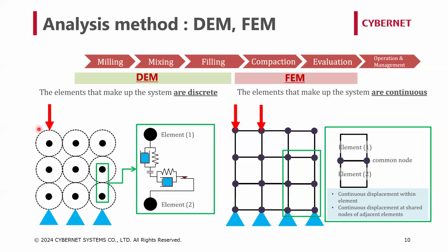When particles are compressed from the tightly packed state, the particles cannot move, and the deformation becomes apparent. To analyze this state, DEM can also express stiffness behavior. Rheological elements such as dashpots and sliders can also be included to easily simulate the viscous and plastic behavior of materials.